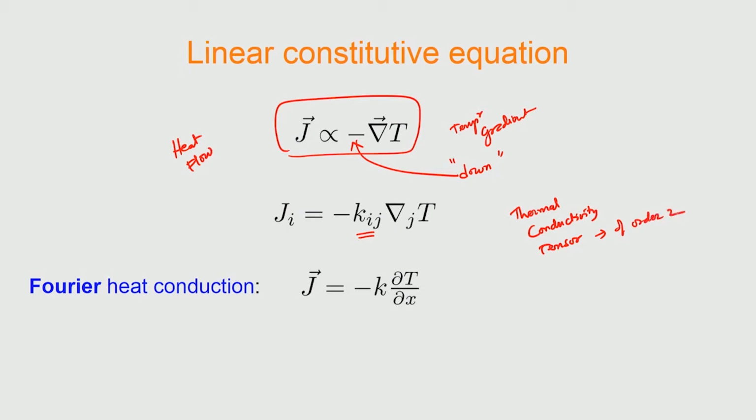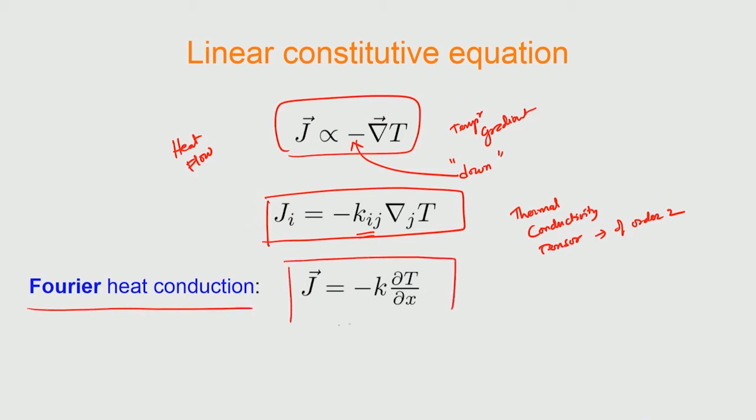Okay. So, that is what we can conclude here, and we have seen this linear constitutive relationship actually come out with a name, Fourier heat conduction, where the heat flux is given as proportional to the temperature gradient, where the proportionality constant is k. Now, normally k is taken as a constant, but we know that the most general form of writing this relationship is where k is actually a tensor of order 2. K is actually a symmetric one also, as we have discussed earlier. This is because of Onsager's principle. Okay. So, Kij is a symmetric tensor.